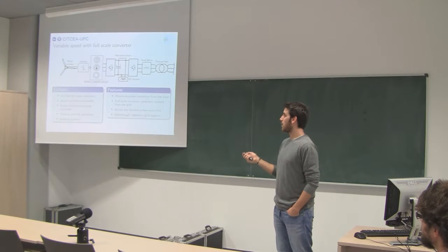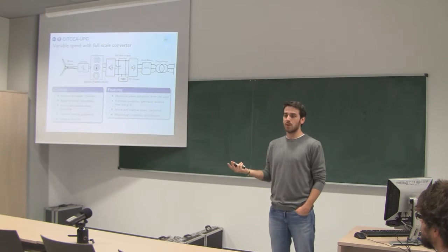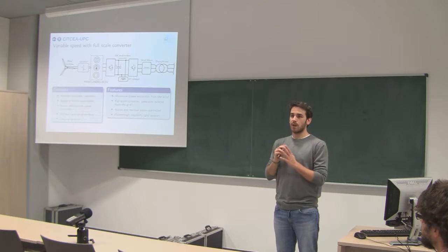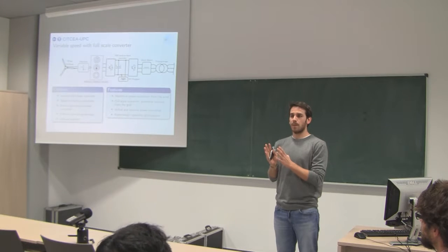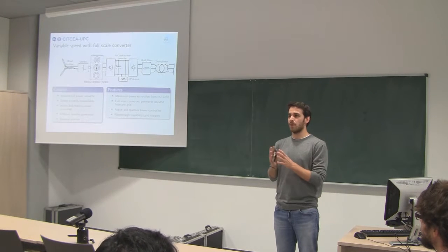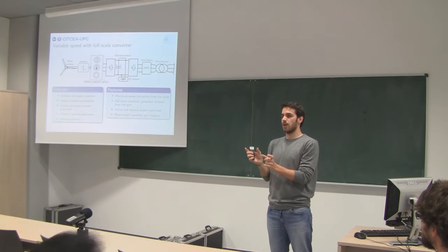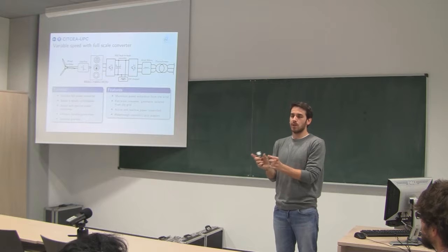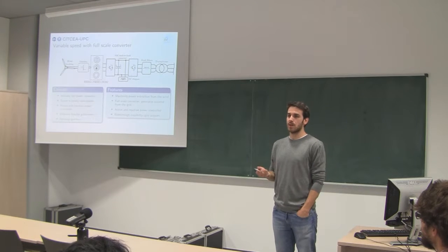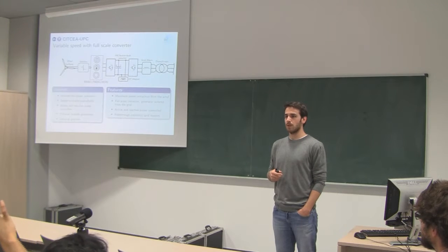These converters are VSC technology, so they are based on IGBTs. It depends on your converter capability. Of course, you will have a converter, for example, rated for 6 kVA, something like that. So if you are injecting a certain amount of active power, you will only be able to inject a certain amount of reactive power, but you are still able to do that.